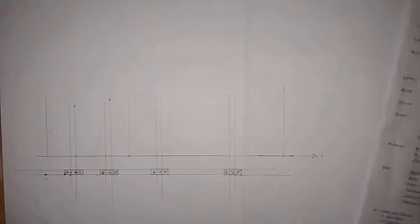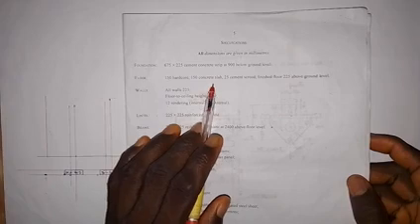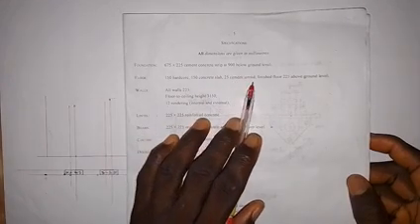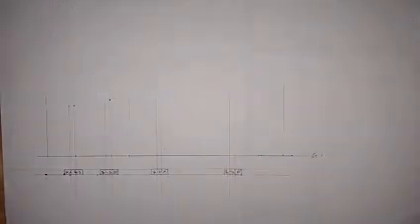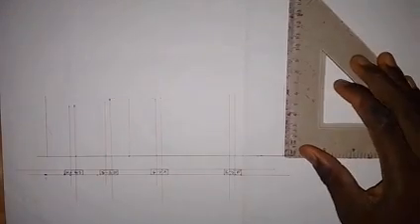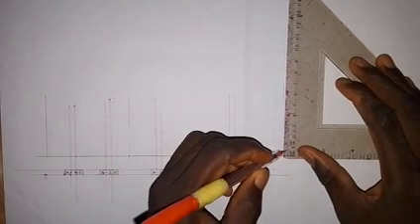So now let's go to the floor. For the floor, as we have in the specifications, 150 hardcore, 150 concrete slab, 25 cement screed, finished floor 225 above ground level. If we divide 225 by 50, that will give us 4.5. So we are going to take a measurement of 5 millimeters above the ground level, as we are told that finished floor is 225 above the ground level. So we take 5 millimeters up.